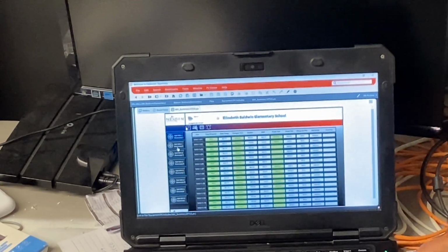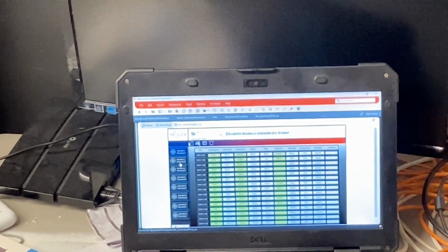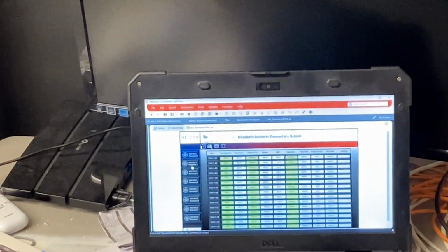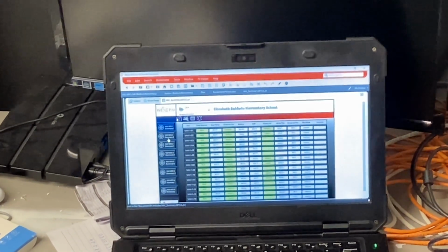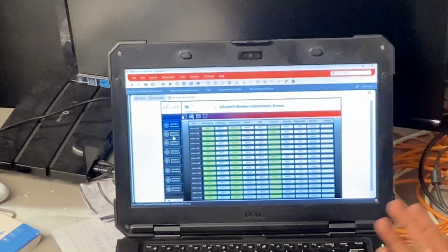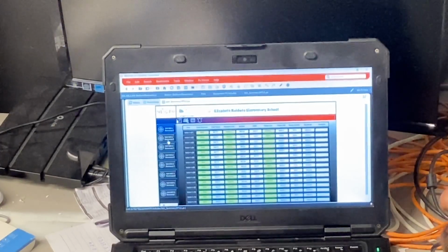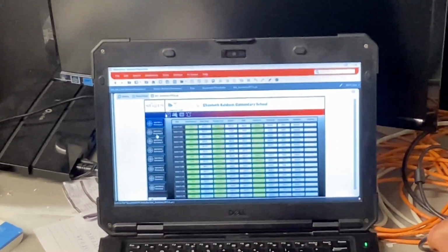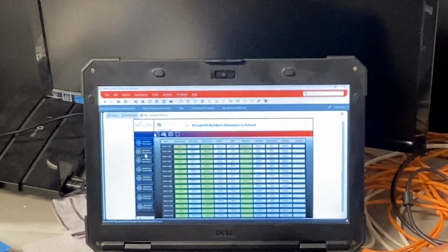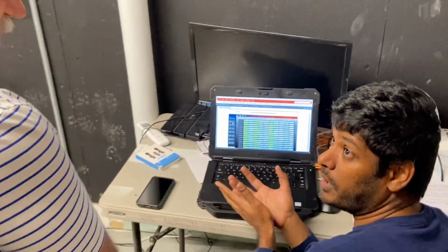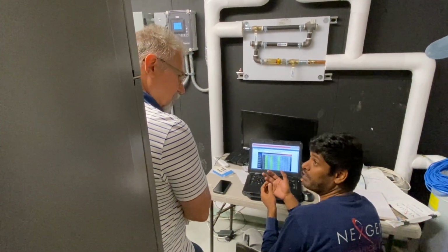Let's touch upon the operation of the VAV. It's going to have its minimum and maximum CFM for the airflow set point. If it is cooling, it's going to range from minimum cooling set point to maximum cooling set point. And if it is heating, the same, minimum heating set point to maximum heating set point on the airflow. During normal operation, let's say my heat set point is 68, and cooling set point is 72, and my space temperature is 70, which is in between. So I'll be in a vent mode, basically doing only the minimum CFM, right?